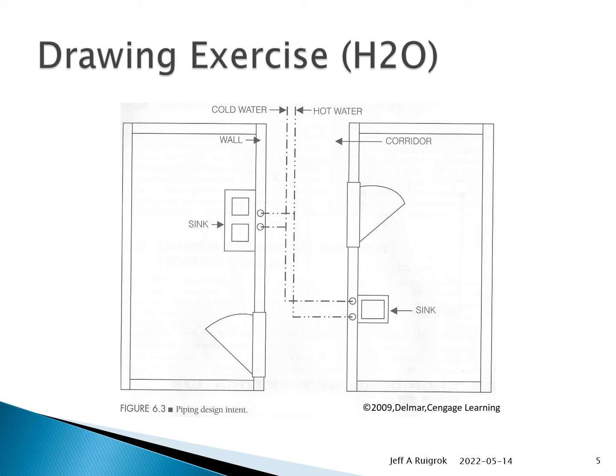So this is a little exercise we have. I'm just going to sketch this one out. If you prefer to do your own work, stop this video for a second or freeze this video and try and draw this in isometric, which is what I'm going to do. Just as a way of explanation for what I'm looking at here, I have some hot and cold water distribution piping. So that's the supply piping. The double dashes is for hot, the single dash is for cold.